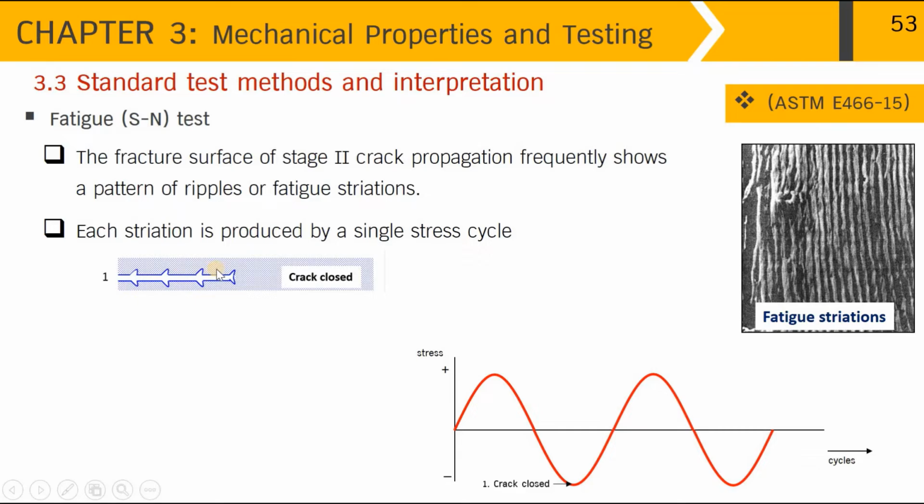First, looking at the cross-section of the fatigue crack over here. Over here is the upper crack surface, and down here is the lower crack surface. At the start, we have 1, 2, 3, 4. So, there are 4 striations at the first start. Over here, we can see that the metal is subject to a minimum load, and the crack is in the closed position, which is along here at the bottom of the curve.